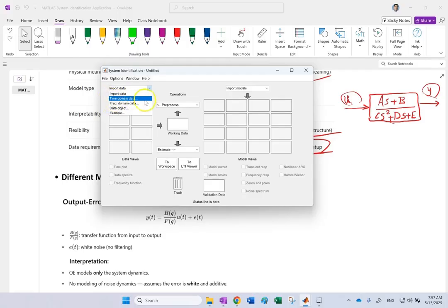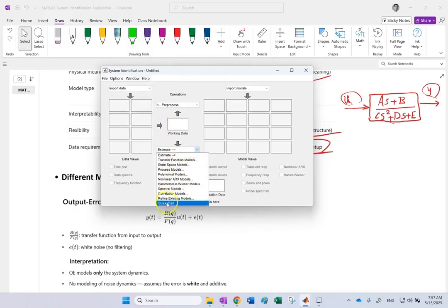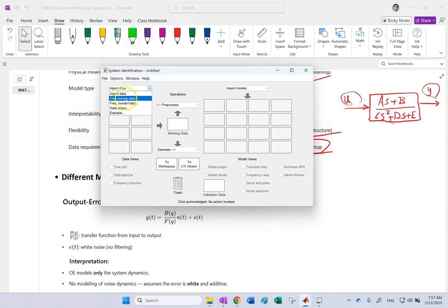Okay, so time domain is the one that fits all of the different models that I'll show you. But frequency domain has limitations on which ones you can apply it to. For instance, if you want to apply it to nonlinear ARX models, it has to be time data. It cannot be frequency data. And I'll show you how to put those data, time or frequency, U and Y together and create what we call a system identification object, which puts those under one single object, and then...